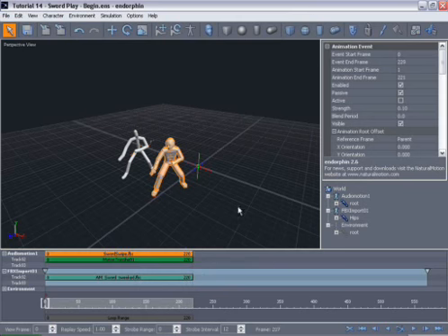Now in this animation event's property view, set the animation start frame to 0, and now turn on active, and this is the setting which makes this animation event an active animation, so that the character will attempt to use its muscle system to match the imported animation. And in the animation event's property view we can increase the strength of those muscles to increase his ability to match the imported animation. So we'll change the strength value from 0.1 to 1.